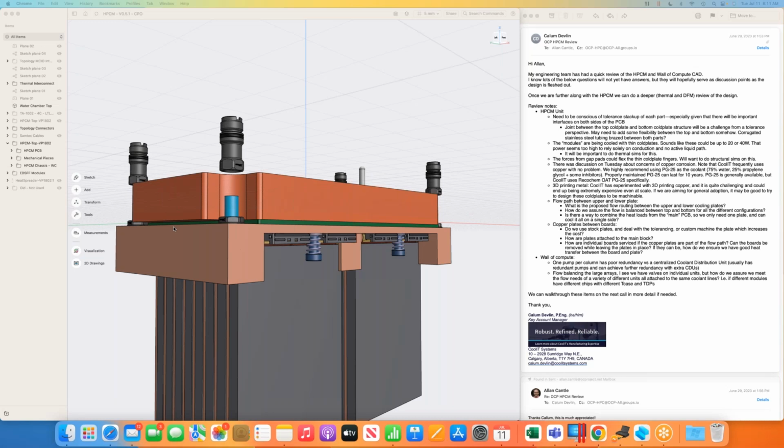No, brazing would make it quite hard from a tolerance perspective. A rubber seal joint becomes quite rigid as well, unless it's a flexible rubber material. Normally a rubber gasket seal is still a rigid joint screwed together, whereas we likely need something to eat up that stackup. So normally, if you have the space, you'd maybe connect those passages with rubber tubing or something like that.